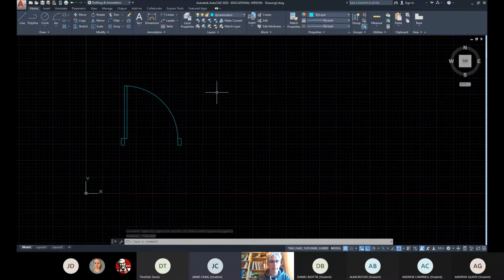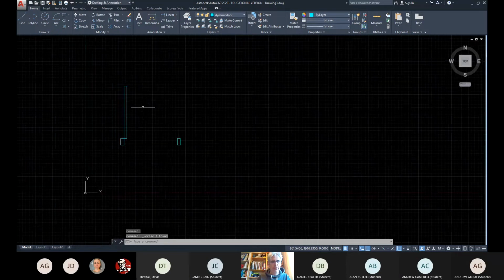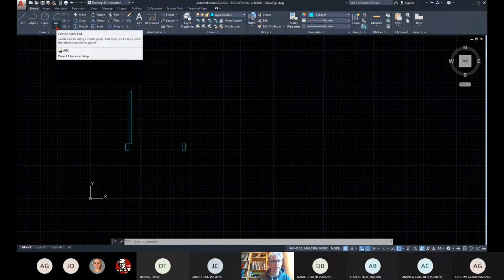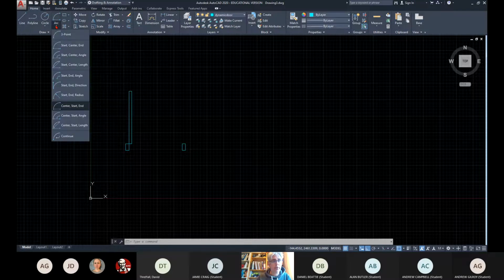Can you do the arc thing again? Pardon? Can you do the arc thing again? Yep. Right, so you got this bit here, Jimmy, yeah? Aye. Okay, go to arc, go to the little downward arrow underneath arc. Remember, this is all on your videos, okay? Aye, just because my layout's so different to everything else. Okay. Click on the downward arrow, go to center, start, end.